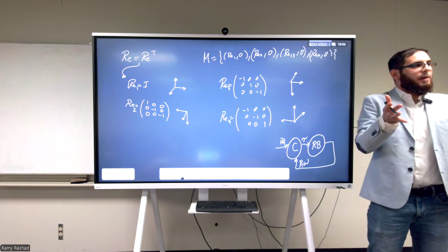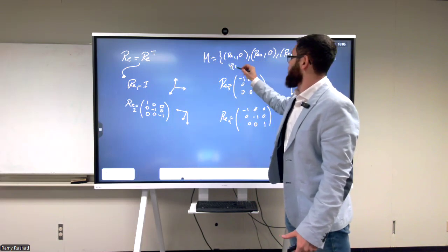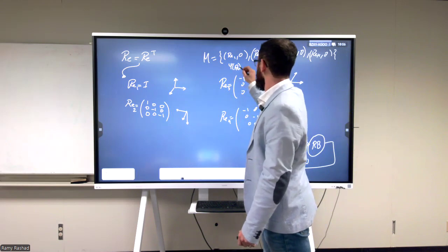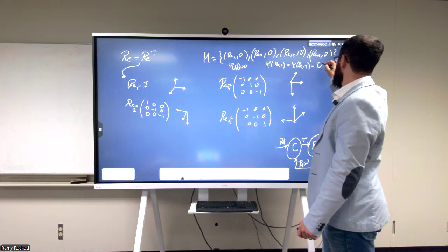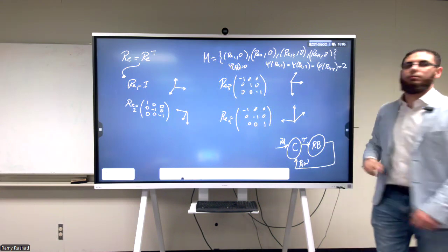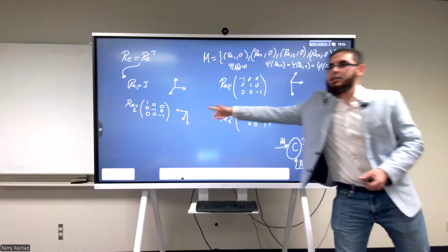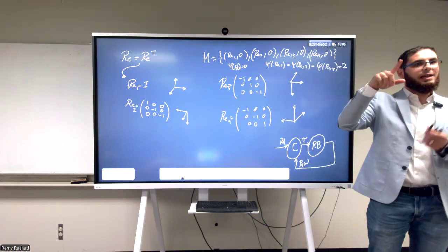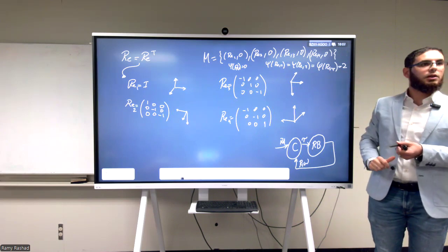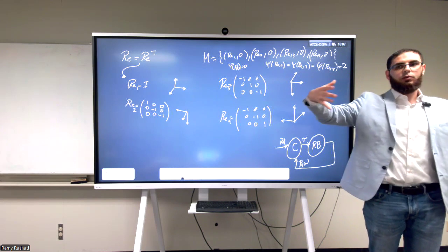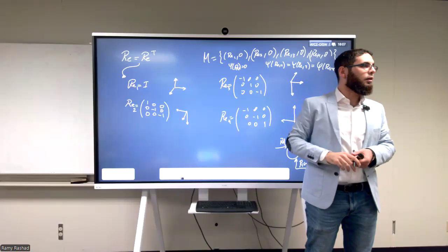We looked at a smaller space, not the whole state space, but a smaller one. And if you go back to the Lyapunov function, we see that psi at this equilibrium point, psi of R_E1, is equal to 0. Psi of R_E2, psi of R_E3, and psi of R_E4 are all equal to 2. Because the angle theta between R and R desired is pi. You see, each one of these is a rotation around one of the axes by 180 degrees. So the theta, which is the angle between R and R desired, is pi. And 1 minus cosine of pi is equal to 2. So this is this term. So simply, if I look at the V, the Lyapunov function, and I try to make the set smaller by taking only values that are less than 2, the only equilibrium point I'm going to have is this one, and then I can prove global asymptotic stability.